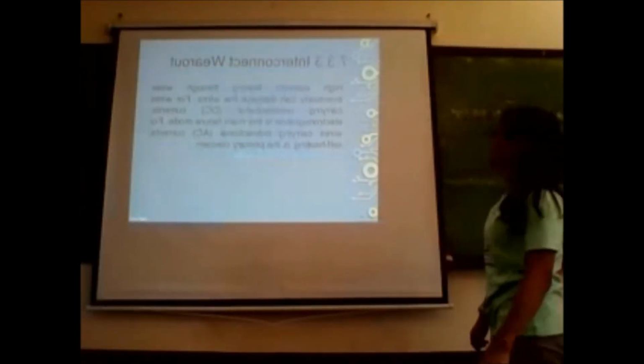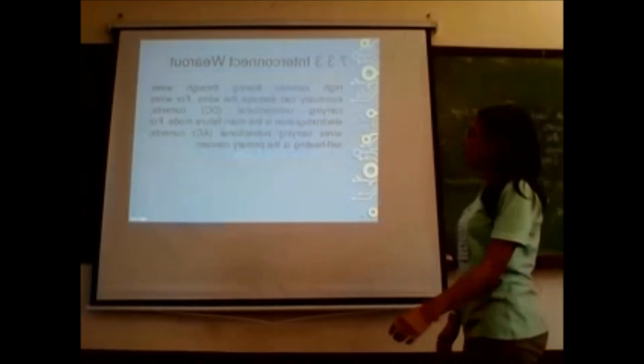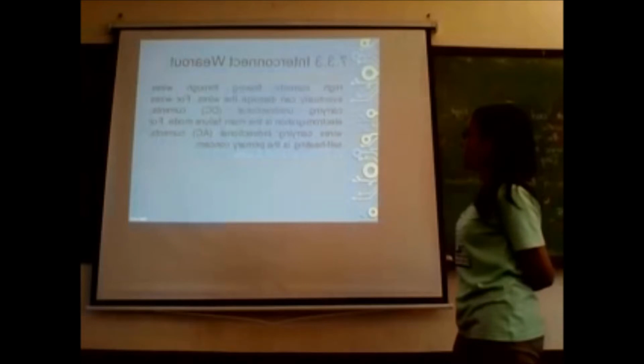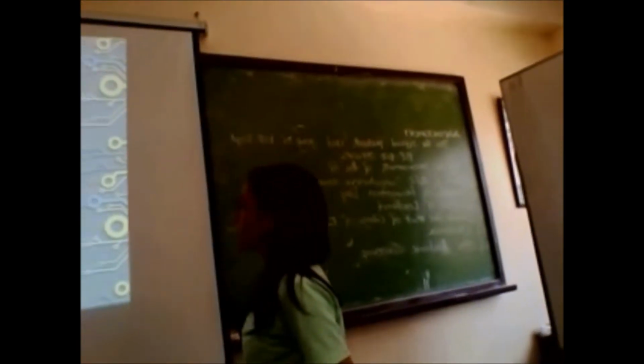Interconnect wear-out. High currents flowing through wires eventually can damage the wires. For wires carrying unidirectional or DC current, electromigration is the main failure mode. For wires carrying bidirectional or AC currents, self-heating is the primary concern. Electromigration.